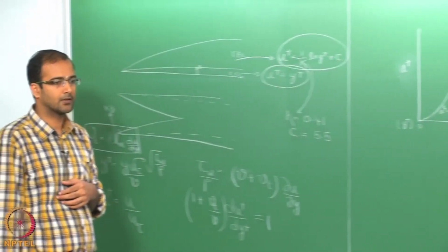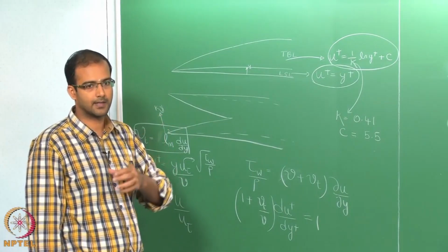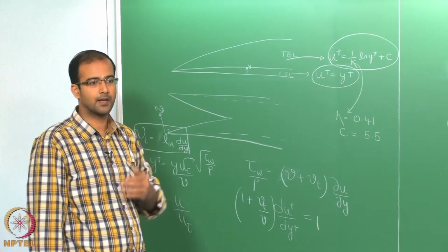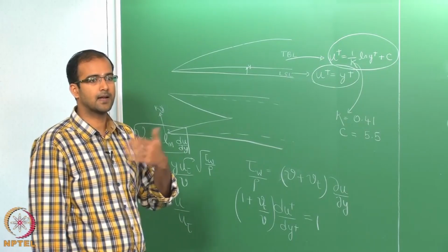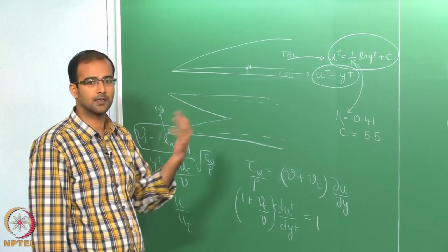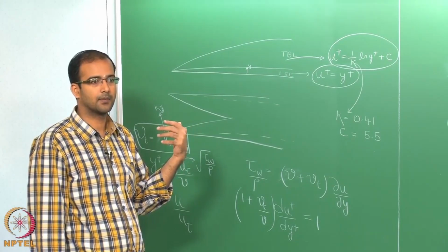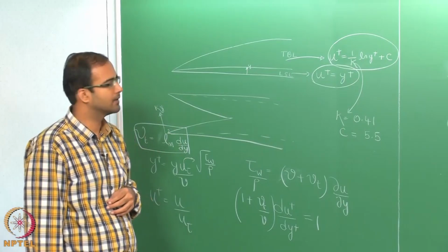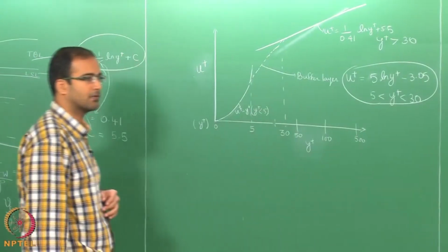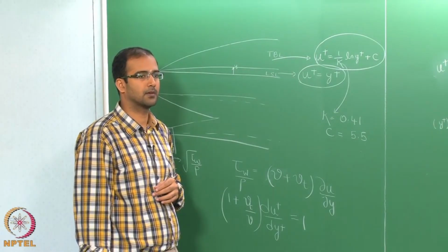Of course, you cannot really visualize this or see this in experiments, but this is how it is conceptualized. So, definitely the viscous sublayer exists, but how the transition happens, it is all concepts. I mean this is what has been widely accepted, because it is reasonably a good patchwork rather than complicating it further. So, this is a classically accepted variation of velocity profile from the wall all the way to the fully developed fully turbulent boundary layer.